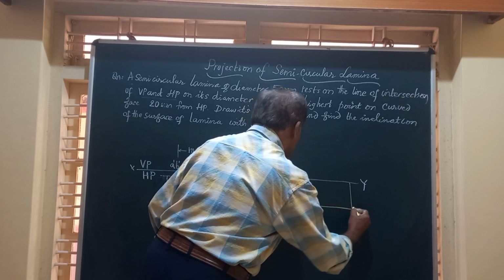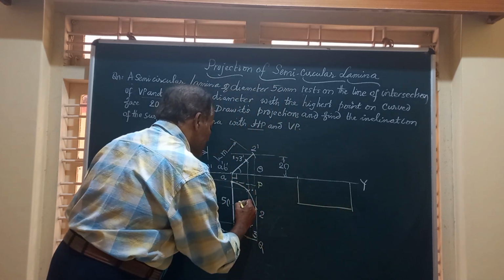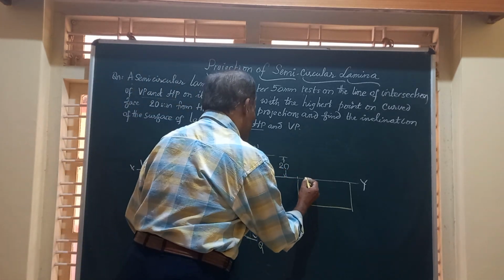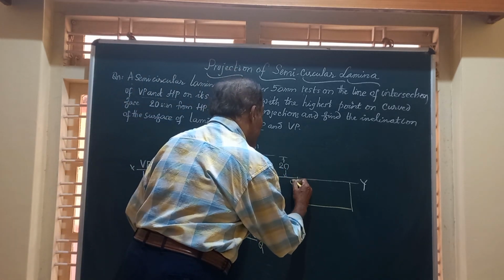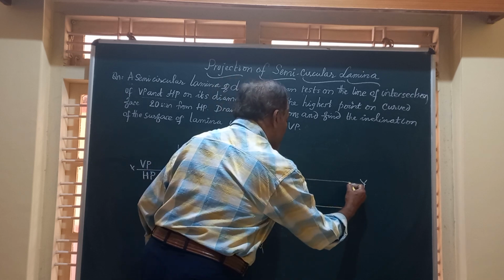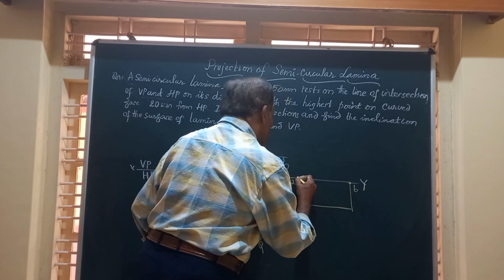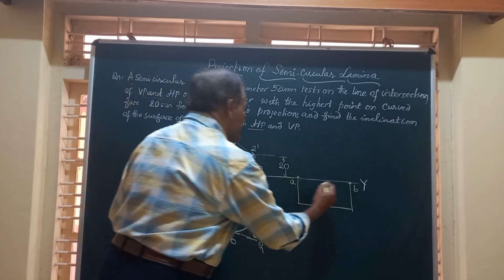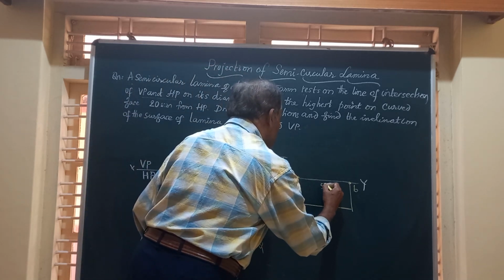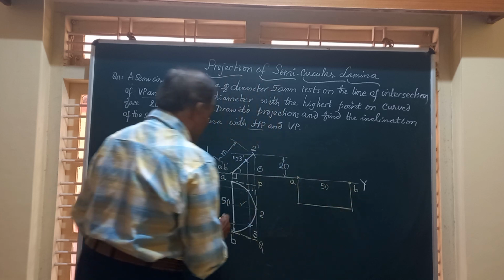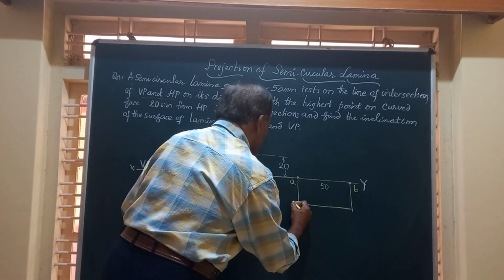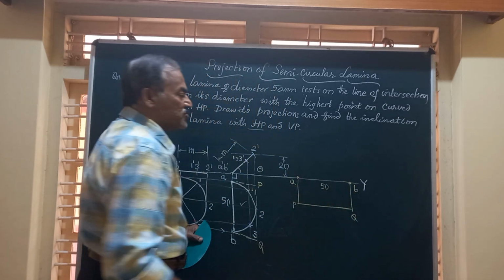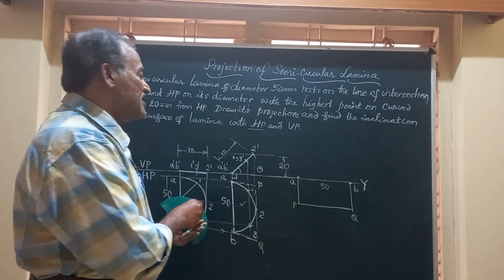So this figure I am going to draw here should be the same as this. So this is point A, this is point A, this is point B. Obviously this is going to be 50 millimeter. So AB is 50. Then we have got PQ. This is PQ in the box. So this box has to be drawn using thin lines.